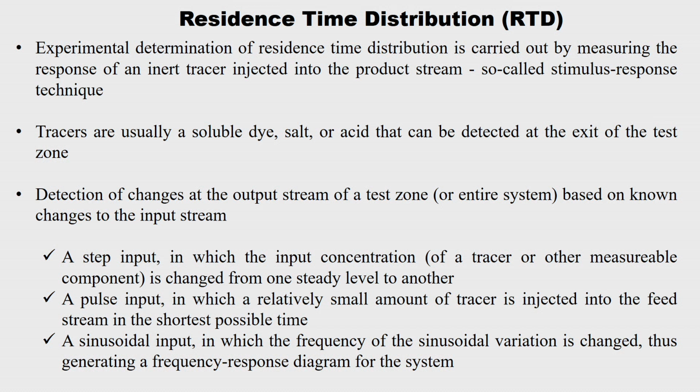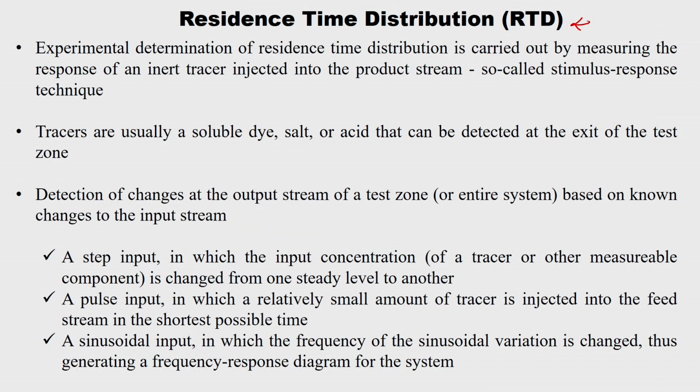And the next important characteristic is residence time distribution. This is how much time my fluid particle spends inside the tube. Why is it important here? In previous thermal processing we have not discussed it, but here it is a pumpable fluid in continuous flow, and also a liquid food product or liquid with particulates. So, as per the FDA or CFR or the GMP, each point, for example, if you are pasteurizing milk, each food particle of the milk should be at the pasteurization temperature or sterilization temperature.